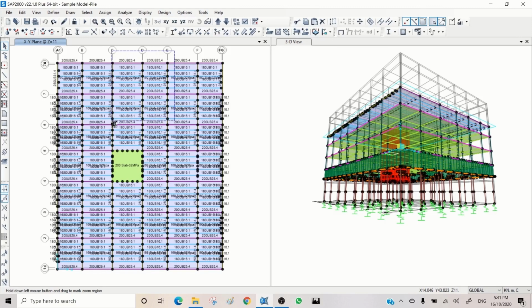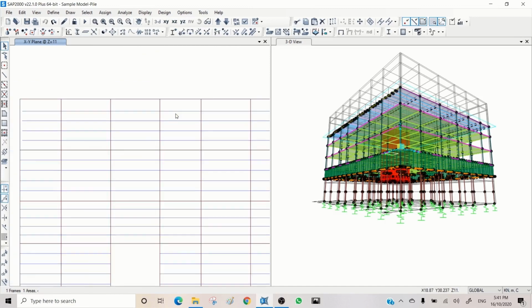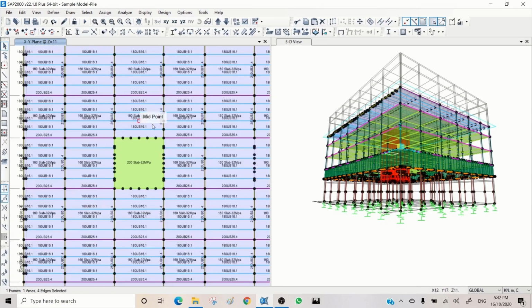The arrangement is 180 UB as a secondary beam, and then 200 UB parallel with the secondary beams, and the main load bearing beams are 250 UB. I introduced them just to save time. What we have in this area is the way the beams are being supported by shell, which may not transfer load properly to the lift wall we have in the middle of the building.